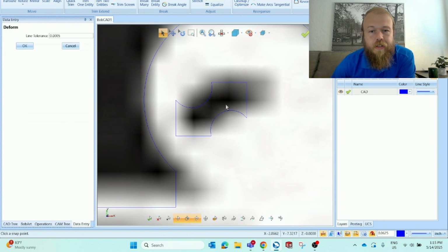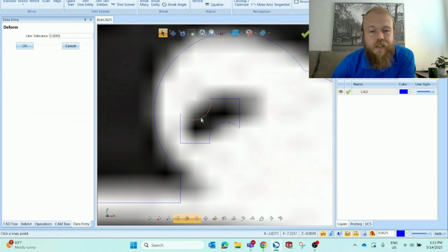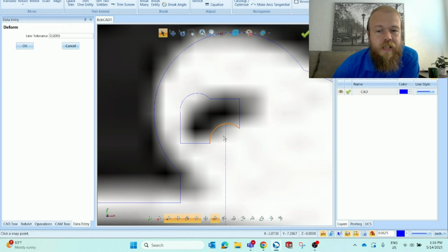I'm going to go here to where the nostril is for his beak and click on these arcs here and change the curvature of the arcs to make them more of a straight line here. Now I can see it jumps on me back and forth here with the arc. If I want to change how it's so choppy like that, I go down to the bottom right and I can click on Snap Increment. So turn that off. And I'm going to turn off all of the icons down at the bottom here for my XY tracking and for my snap increments.